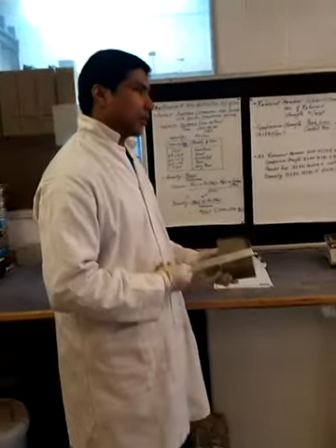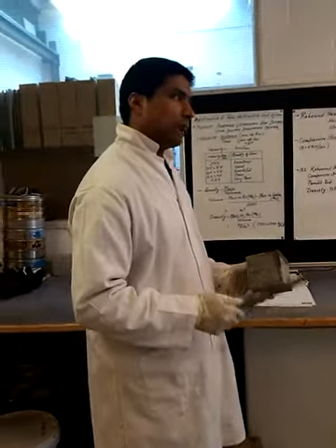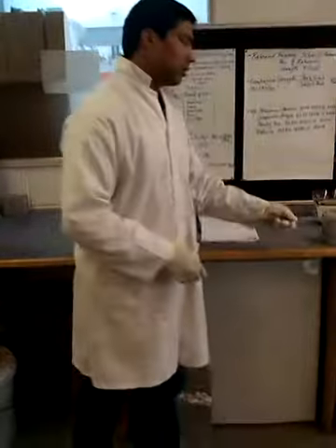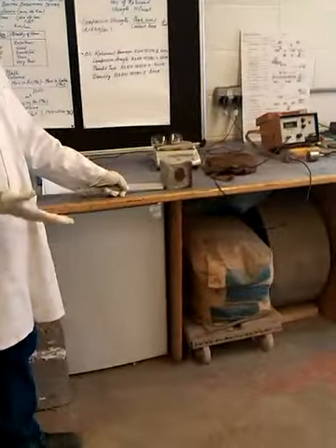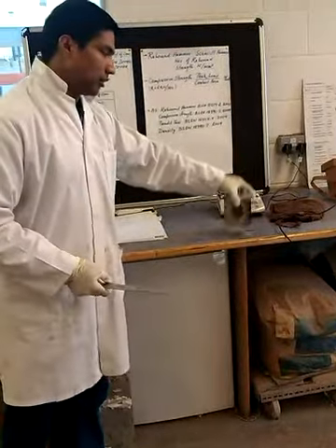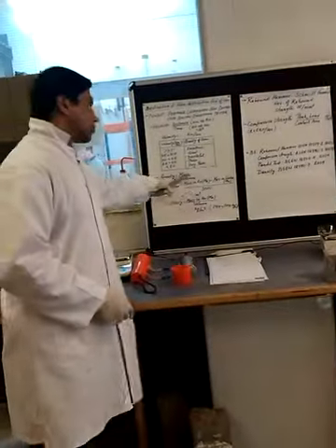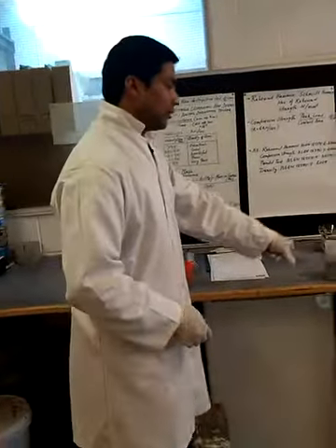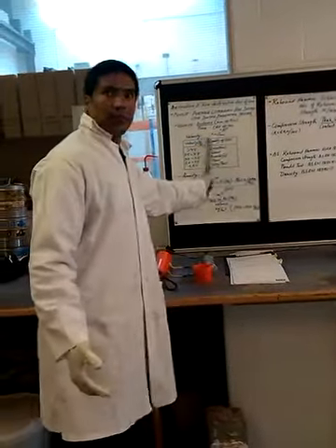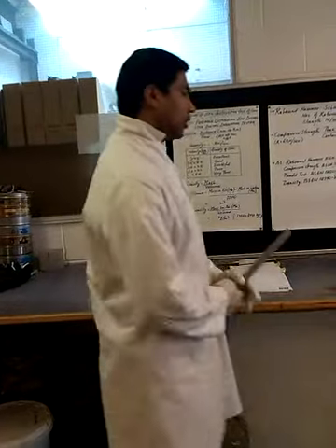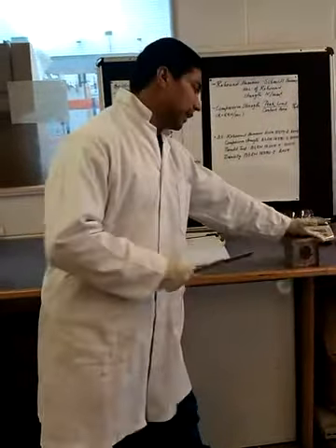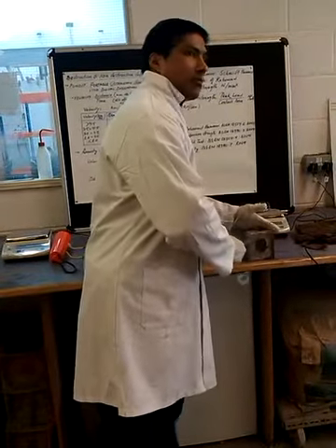what's the density of the concrete. Normally, density of the concrete can be calculated in 2 ways. One is just measuring the length, breadth, and height. That will give you the volume, right? And mass of the concrete, right? So mass density is mass by volume. So mass and this measurement will give you the volume, and mass divided by volume gives you the density. That is one way. The other way is water displacement method, which is more accurate than using the measurement method.